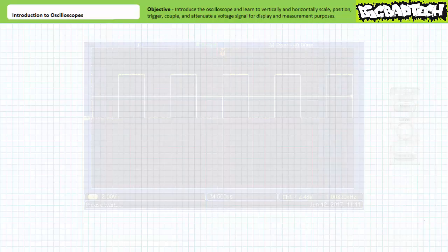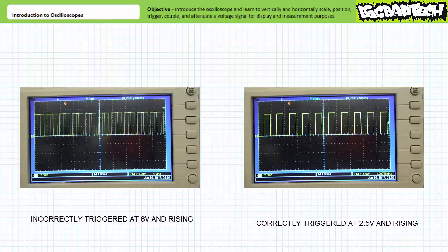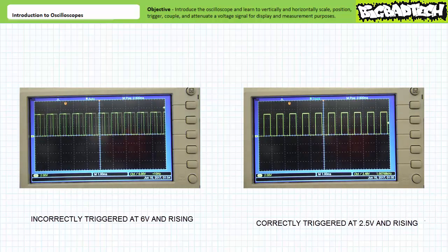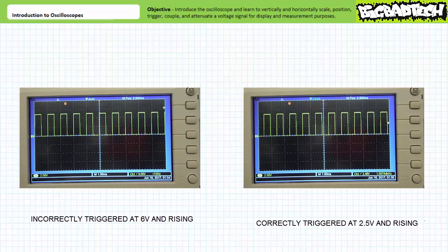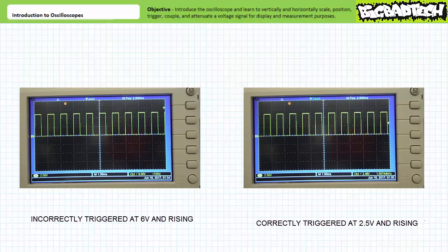Display problems arise when a user attempts to establish a triggering condition that the waveform never achieves. For our sample test waveform, triggering at, let's say, 6 volts going positive would mean the oscilloscope never establishes a 1 beat, since the waveform under inspection tops out at 5 volts. Given this unattainable condition, the oscilloscope loses the beat and the display starts this annoying drift. The drift is hard to capture on a still picture, but a video clip shows the jitter a little better. This annoying effect is amplified when viewing faster signals using a larger time span on the horizontal axis. Long story short, triggering off nonsense conditions yields astable results.